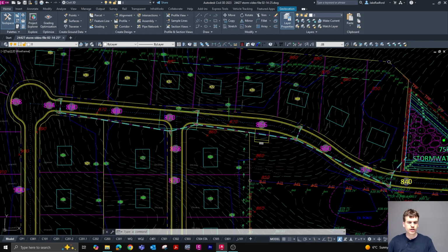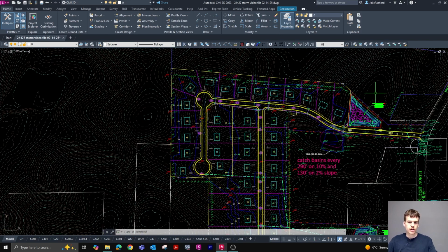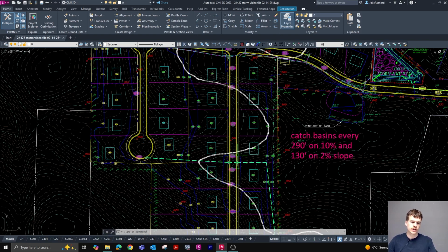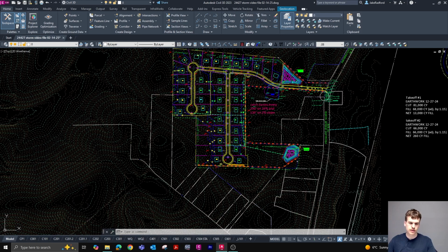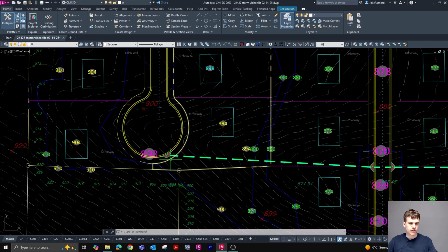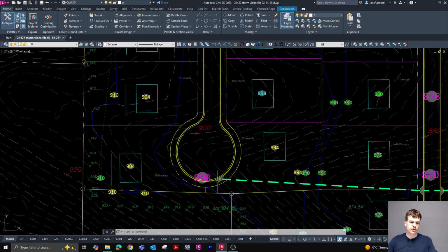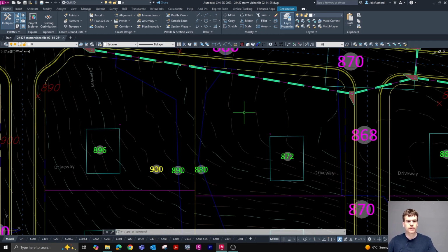And we're just going to go ahead and take a second to talk about some of the key pieces of information you need to know before you create your pipe network. So one of the key things is that you cannot join structures and pipes from two different pipe networks together. So if for whatever reason our stormwater design changed and we created a pipe network, so we had our pipe network B down here on the southern portion of the site and our pipe network A up here on the northern portion of the site, and we wanted to tie in, say, this structure no longer runs down to this guy, it actually runs up to this guy. This structure would have to get moved from our pipe network B up to our pipe network A, or else they won't join correctly.